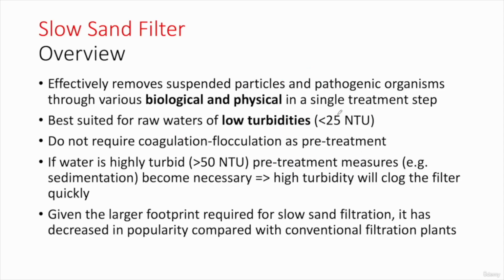The slow sand filter is an excellent method to remove suspended particles as well as pathogenic organisms. And this is the major difference between this type of filtration and rapid sand filtration. Why do we have the removal of pathogens like bacteria, viruses, and protozoa? Because we have biological activity. We will see what triggers this biological activity later on. And we also have physical removal, because of the presence of a sand media that will trap the suspended solids.